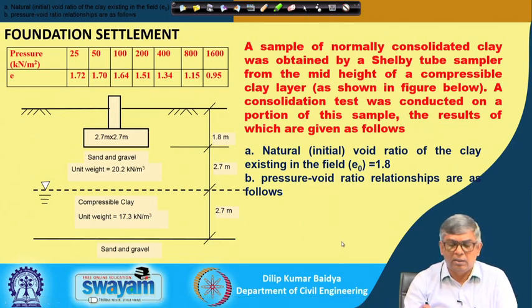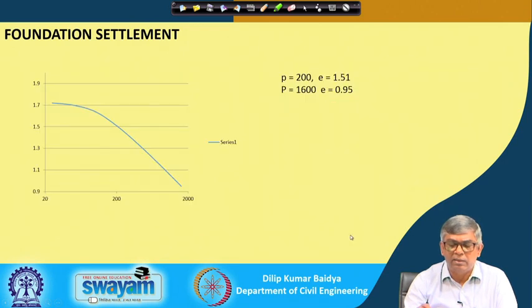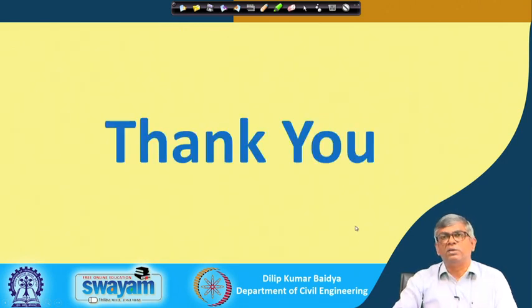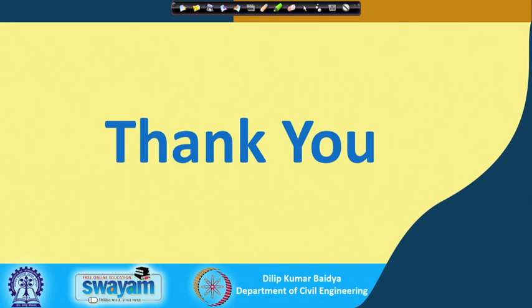With this, only one part is left, which may take just 1 or 2 minutes, as not much information is available. I initially mentioned that settlement is a combination of 3 parts: initial, then consolidation, and then secondary compression. For secondary compression not much is available; I could have brought it today, but there is some empirical method to calculate it, and sometime I will take that one. It is not very important either. Otherwise, the settlement of footing considering various aspects I have already done.